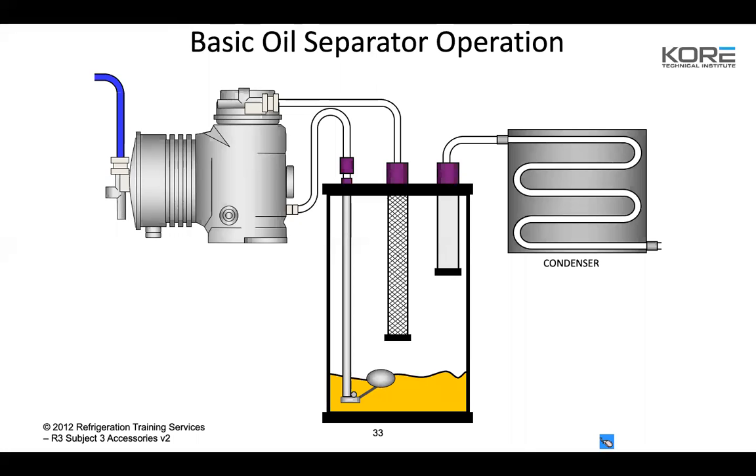Where we usually see a problem with these is this float gets really gummed up with debris and filings. So we usually have to drop the bottom plate out of those low pressure oil float systems and clean this float right here, and it's attached to the bottom plate. Or what we've seen now 3 times in the past 5 years is this screen right here comes detached inside, and it actually comes down and pins the float down, or pins it to where it won't open.